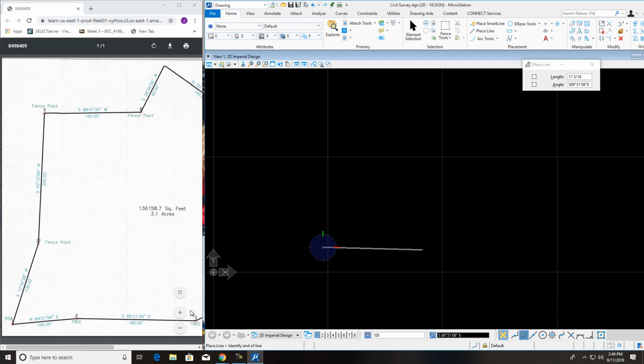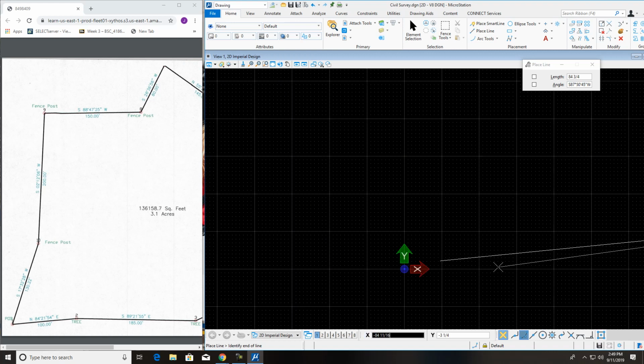Now, I'm going to show you how to do this one. Now, you can leave it like that and just tab across and put in the numbers. And that first one is 84, 21, 54. And you got that put in there, and that's going southeast. I want to go northeast. So I want to come back over here, hit northeast, and it'll put it in for me. And all I have to do is just click. And there it is.